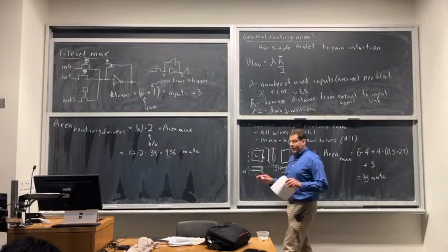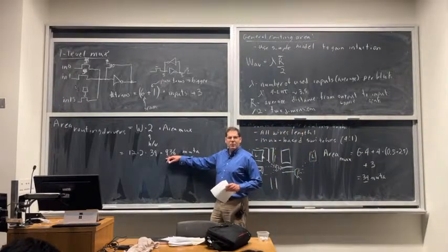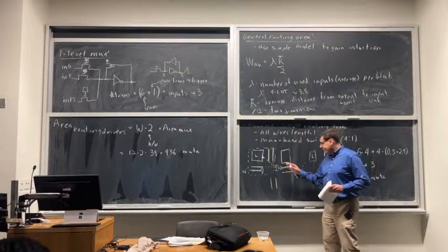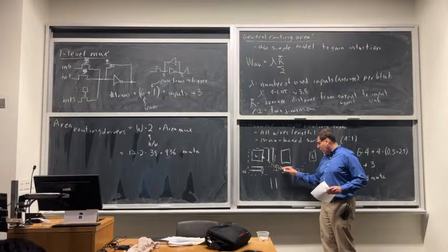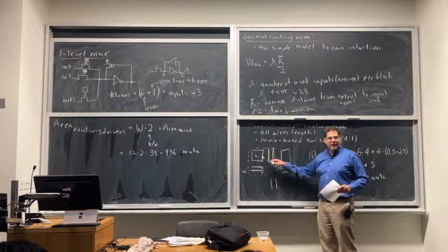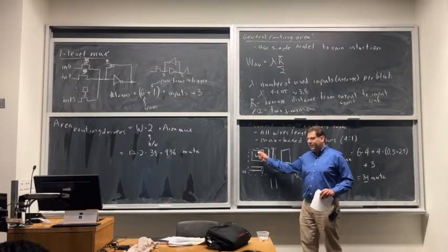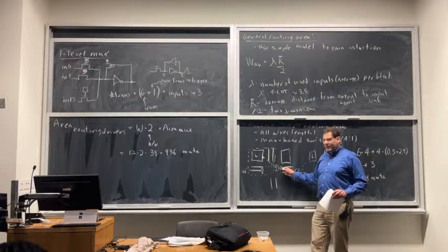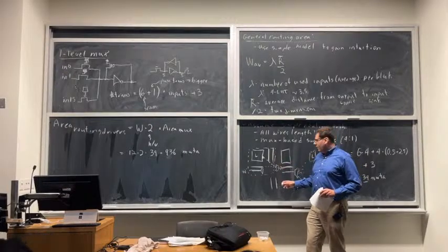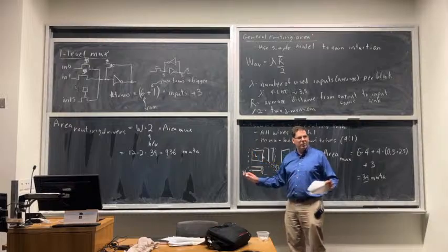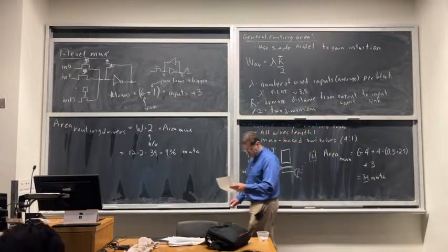Okay, so it's actually pretty big, right? So this routing area adds up pretty quickly. These muxes give us 2 things: the ability to switch from one wire to another, and also the ability to connect outputs into the routing. So we're done now, right? We can do logic in our LUT. We can connect it to our routing. The routing wires can connect to each other, and then those input muxes allow us to get back into the block. So that's all we need. We can now do arbitrary logic.